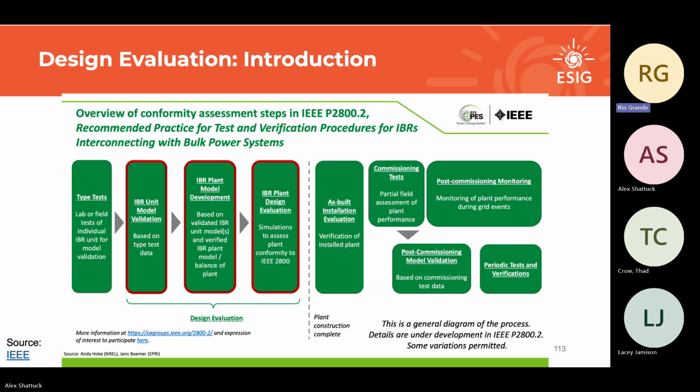So for those of you who are curious about the consecutive faults, the intent is to say if there's a bunch of reclosing or a bunch of similar or close by faults that if you get hot, your converter gets, or your chopper circuit gets hot, or other things get temperature rise, that you trip offline because of that. But models, even the EMT models, don't have thermal things in there.